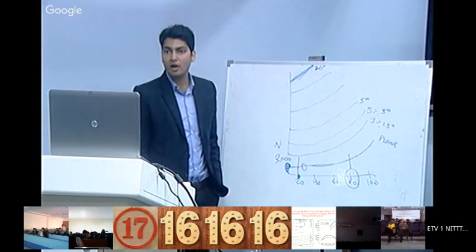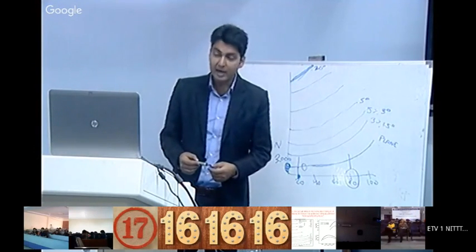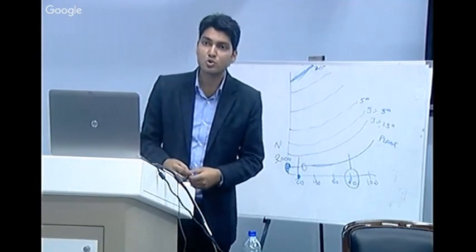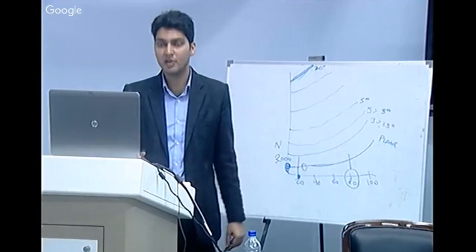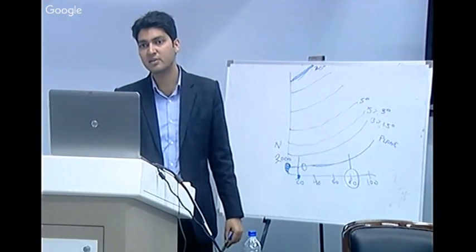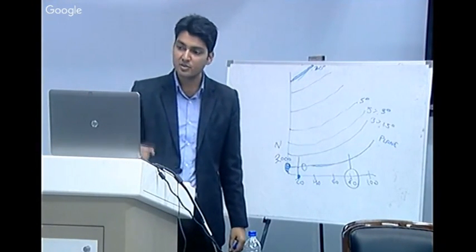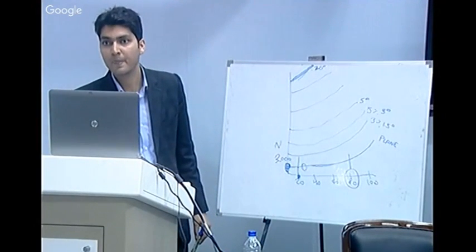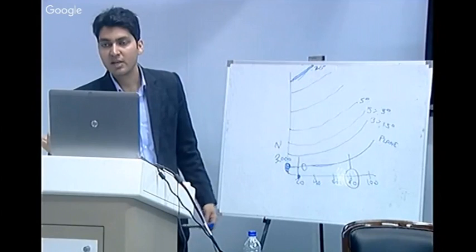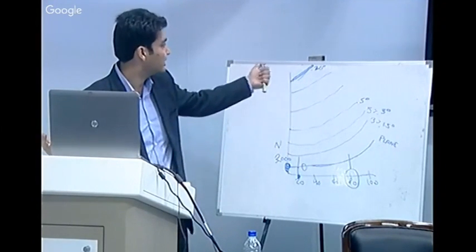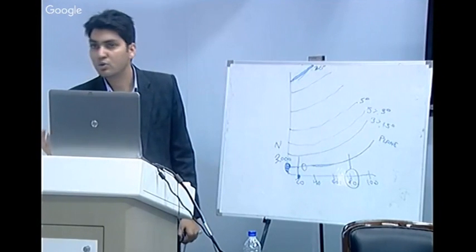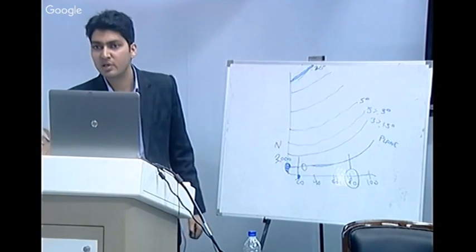My torque requirement only to start up my vehicle is near 200 Newton meter on a plane surface. But my engine is going to produce only 300 Newton meter on the test bed, as seen in the graph of the engine.